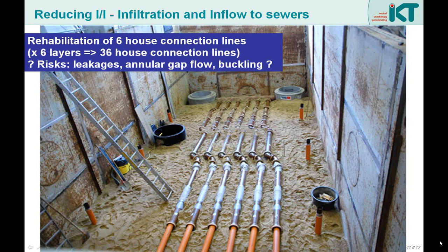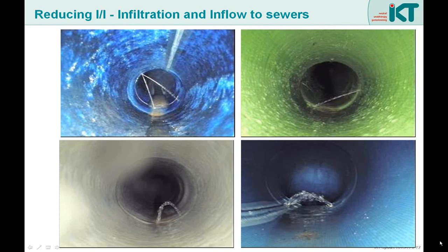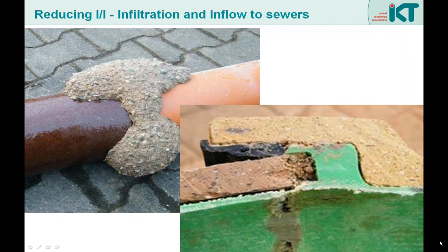However, something else occurred. After the rise of the groundwater level, we observed cracks at bends and joints of most of the products. In consequence, water infiltrated again. The reason was not so simple to identify. We had to dig up the lines to understand.